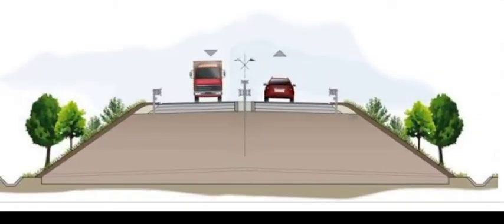The material considered is soil, murram, gravel, or a mixture of these, which are free from organic matter, stems, roots, or any organic ingredients. And before construction, the entire natural ground needs to be cleaned properly. There should not be any small water bodies or weak pockets, right, that need to be stabilized.